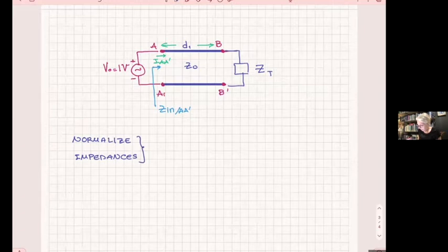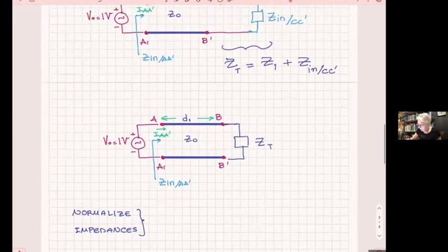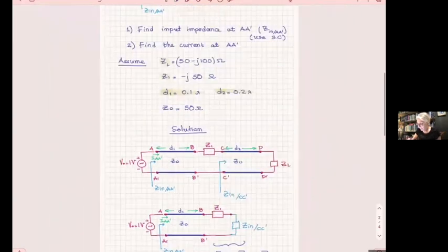All right, which means I will have to take the impedances that were given to me and divide them by Z naught, which is 50. So ZL normalized, I could do it here as a matter of fact. That's where I would normally do it, next to my data, is going to be 1 minus j2. And of course, it loses the units.